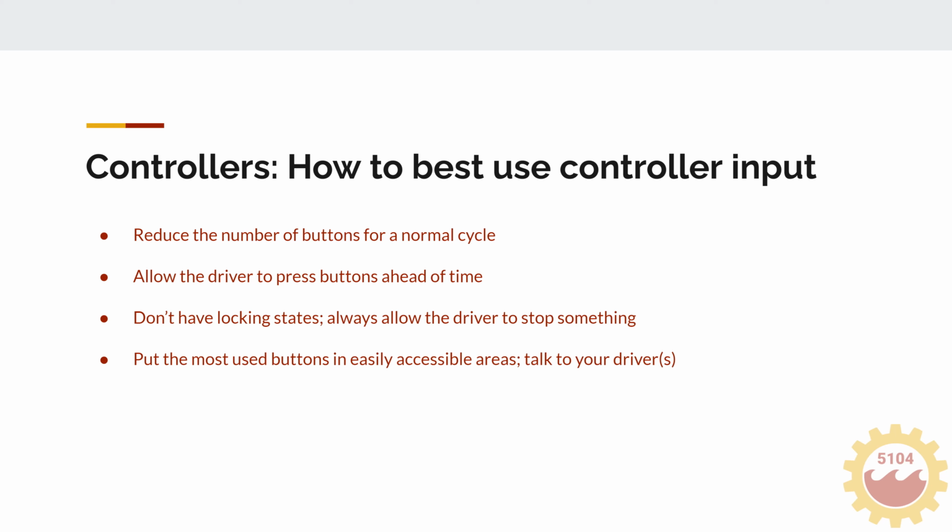So my favorite example is in 2019, we built an off-season robot with an elevator, and in this game, you would lift hatch panels to different heights. So when we're driving to get a hatch panel, we'd be like, okay, we're going to score high. Obviously you can change this later on, but I press the button then, and when you go to place it, you don't have to think. You just press the place button, and it automatically goes to that height. You're not having to press which height you're at and move your fingers around. It's super simple.